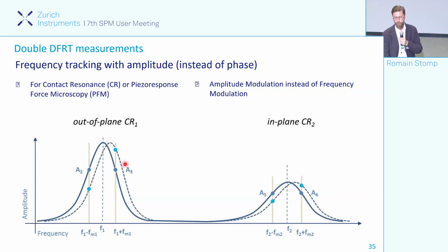And so in this way, you use an amplitude modulated technique. You basically measure sidebands a little bit below and a little bit above the resonance. You take the difference of these, and the difference looks fairly linear in between the two. So that actually gives you a slope, and of course the slope is 0 when you're at the resonance. And once you do this for 1, no one prevents you from doing it for 2 or even more if you want to. That's very convenient because you can track the resonance in this direction, but also the torsional one, simultaneously.